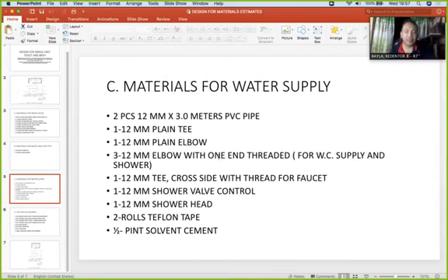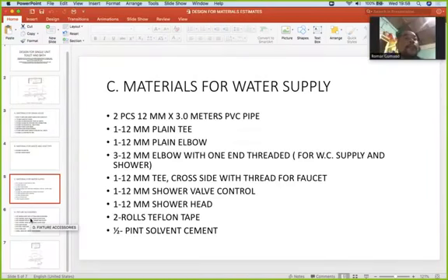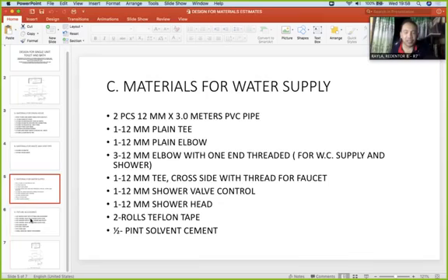Metal threaded fittings are used because of strong pressure, and they can leak too. So it's not advisable to use that. PPR, sir, right? I use PPR, sir? PPR is for water, especially for water in the commercial industry. PPR now, no more PVC, for heating systems, by fusion, because of the pressure. There are also PVC now that can withstand it, but because of improper use of solvent, the solvent often dries up, so again, leaking. That's why normally used is PPR, polypropylene resin.